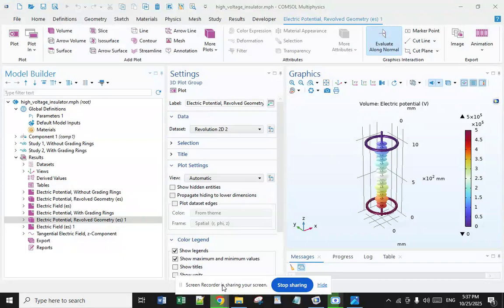And the maintenance and cleaning. Lack of proper and regular maintenance can exacerbate the negative effects of environmental and overload factors. Periodic cleaning of insulators is essential in areas with high contamination, as is inspection for signs of wear or damage.